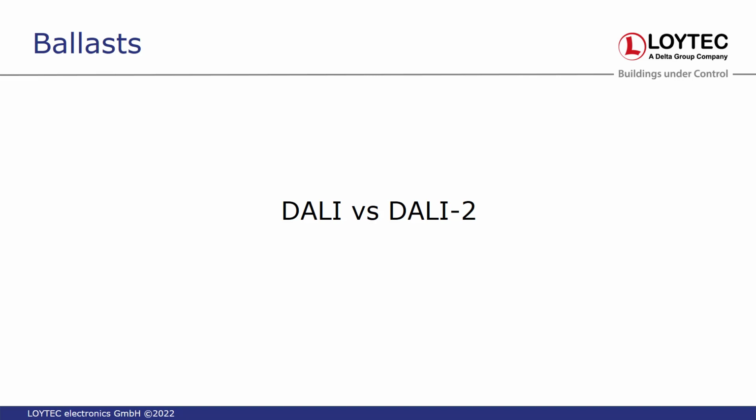But when you have a combination between ballasts and sensors, DALI 2, then the ballast might be confused by the other sensors on the channel, not the L-DALI. For the L-DALI, it doesn't matter. But we have seen such sites actually, where this was an issue.